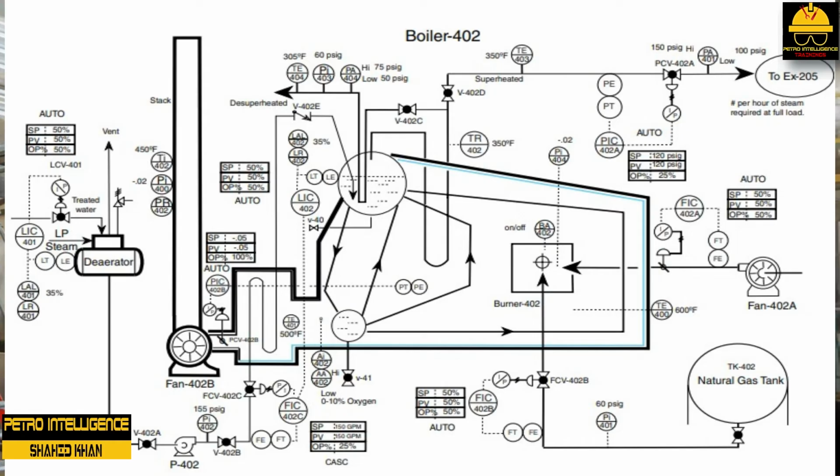Inside the upper steam generating drum of B402, steam and water come into physical contact, saturating the steam. This saturated condition means that for every temperature of water, a corresponding pressure of steam exists. The pressure on the water sets the temperature as long as the steam and water are in contact. Basic boiler design removes the steam from the upper steam water drum and superheats it at essentially the same pressure.